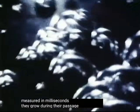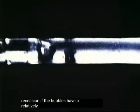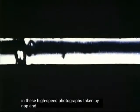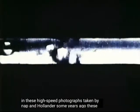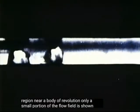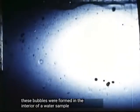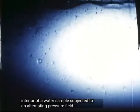They grow during their passage through the low pressure region and then collapse as they enter the region of increasing pressures. If the bubbles have a relatively large initial gas content, they will collapse and then rebound, as in these high-speed photographs taken by Knapp and Hollander some years ago. These bubbles were formed in the low-pressure region near a body of revolution. Only a small portion of the flow field is shown. These bubbles were formed in the interior of a water sample subjected to an alternating pressure field.